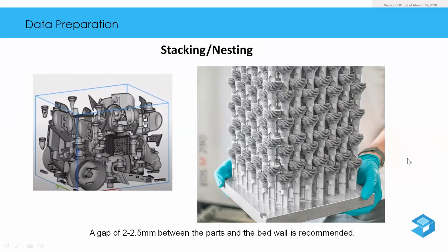A lot of you might not be actually aware of the wire cut EDM process. In metals, in order to secure the part to the bed, it's directly welded together, joined together. So you use a non-traditional machining process called wire cut EDM, in which you'll be cutting using a wire cut EDM machine, and then it will cut off the material from the supports and from the bed, securing each part from the whole 3D printer.